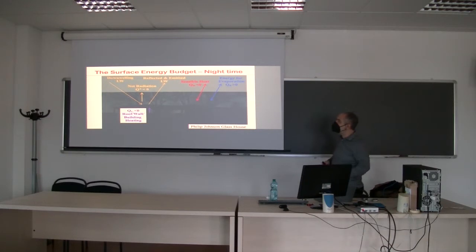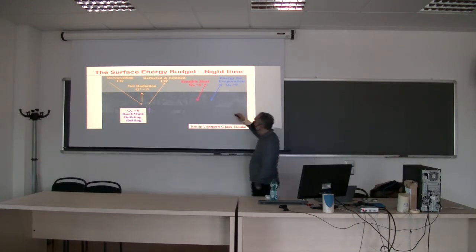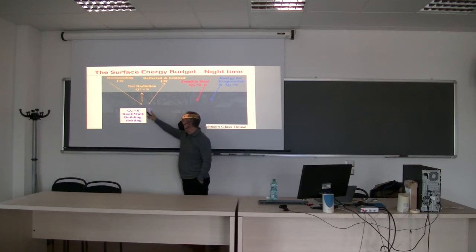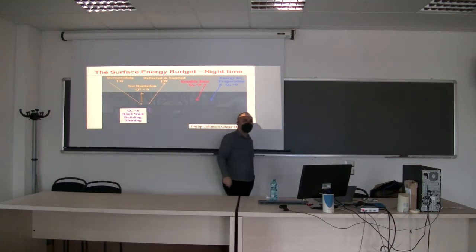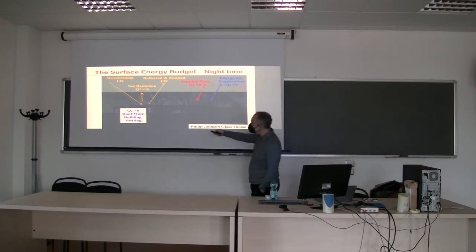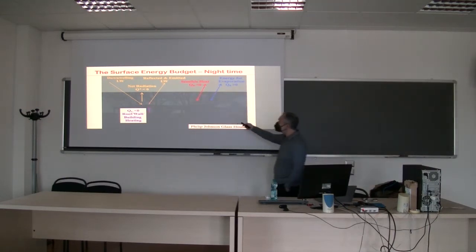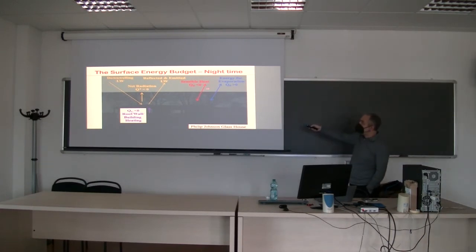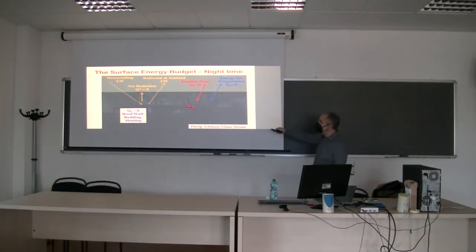Now, where is this energy coming from? You would notice that the roof has heated up during the day, so it's now releasing its heat. So Qg is negative because Qg goes into the interface, and by the convention, we said going into the interface is negative. Negative meaning it's a heat source to this upper interface. So it's going up into the interface. And you will notice that typically the surface is going to be cooler than the atmosphere. So typically QH is going to be negative, meaning the air is heating the surface.